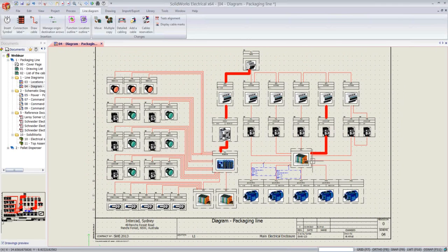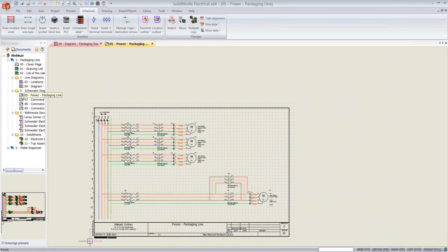We will create a circuit for this motor to be connected to terminal strip X1, and then through terminals X1 we will connect that to contactor K4, circuit breaker Q4, and then we'll also power up this PLC where my cursor is through that transformer T1 and circuit breaker Q6. So let's just open my multi-line schematic.